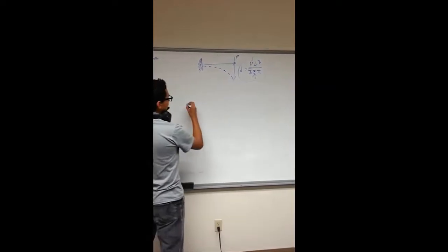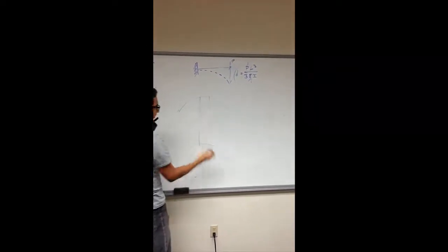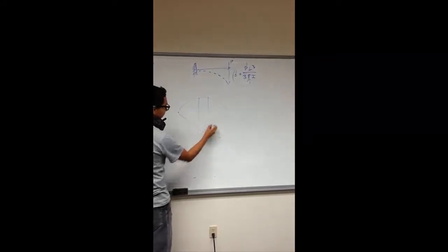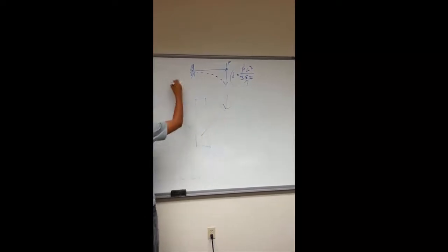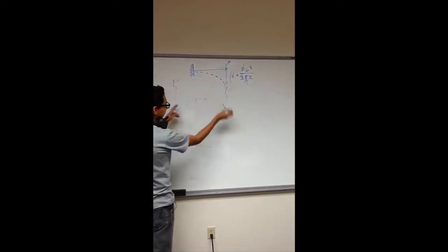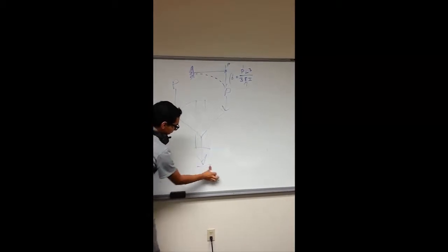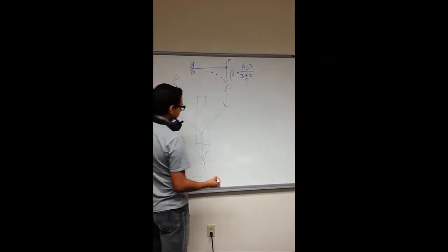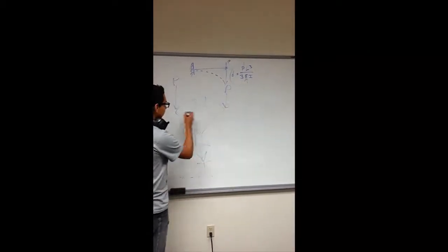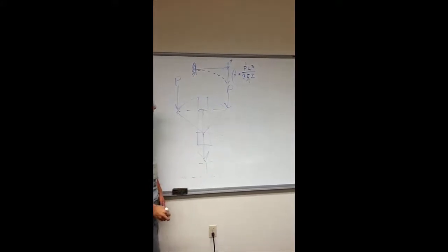The bow is simple enough on our system. It gets pulled back, and there's a pulling force P on each side, basically two cantilever beams, which goes directly into our tension, which is our required force. And through this equation, we can find out how far we need to pull it back to get our required tension and force.